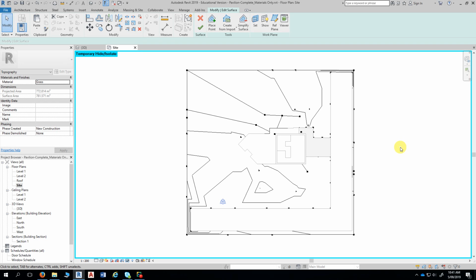And to be honest with you, I only discovered this myself a week ago, because I was thinking there must be some way of manipulating the terrain to suit the pad itself. And it just made sense to trace the pad edges with additional points at certain height elevations, and that would make the terrain curve up and meet the edge of the pad itself. Basically that means that rather than using subregions, we can use pads which are completely flat and look far more realistic.